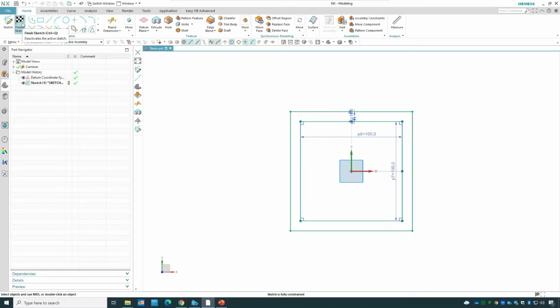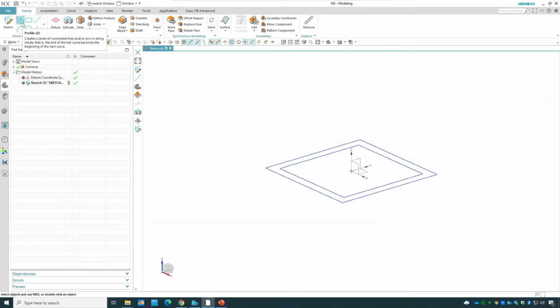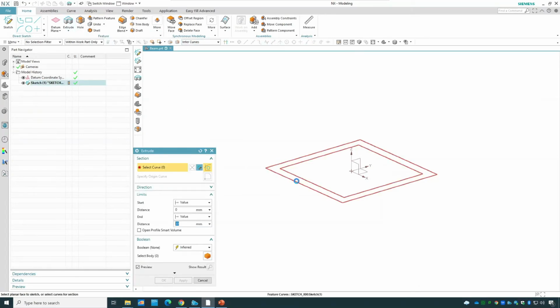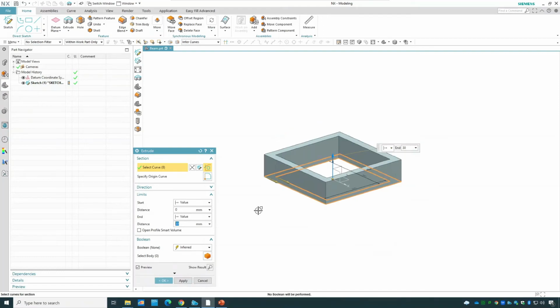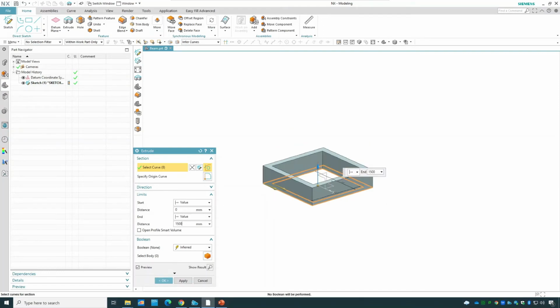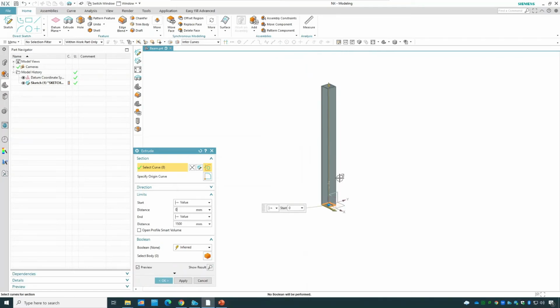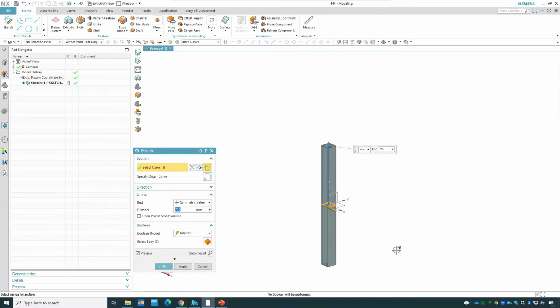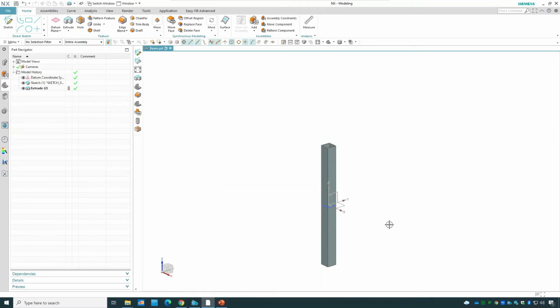I'm gonna click on the finish sketch, and what I'm gonna do, I'm gonna extrude it for the 1500. But if I extrude it like that for 1500, it won't become symmetrical. What I'm gonna do, I'm gonna extrude symmetrical on both directions. So I'm gonna extrude it for 750 on each side, and that would enable me to, once I'm gonna study it later, you can find out what's the reason I'm gonna use this method to have a fully symmetrical, and I'm gonna have a plane in the middle. That would help me a lot on the other part. I'm gonna click on OK.